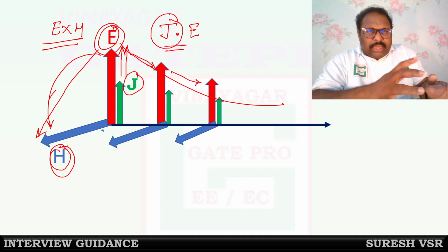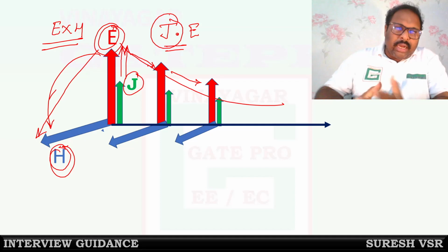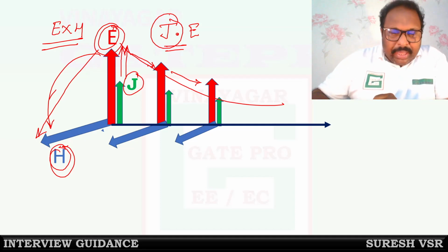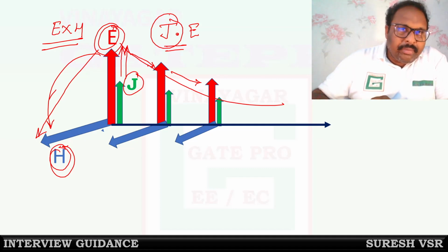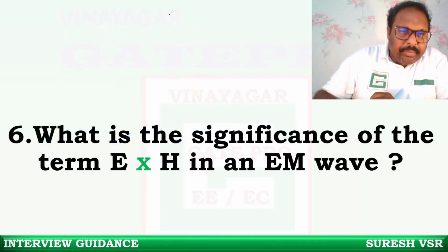So E is producing a J means E is occurring, it's undergoing some loss. And that is because of conductivity, because J is sigma E. So if somebody asks you what is ohmic power, you should say it is the loss power that the material is acquiring because the wave is losing. So wave is losing, material is acquiring, that is what is J dot E.